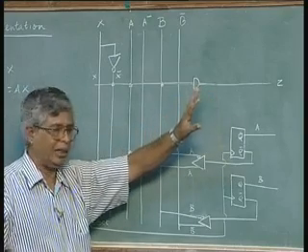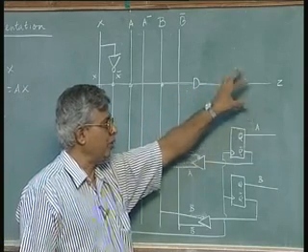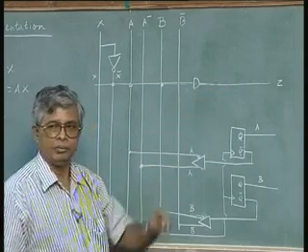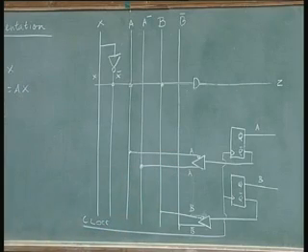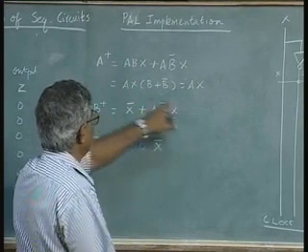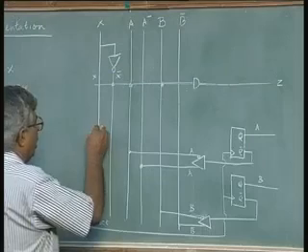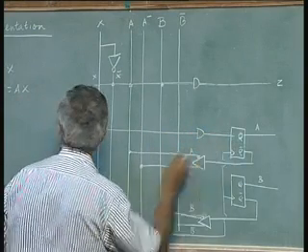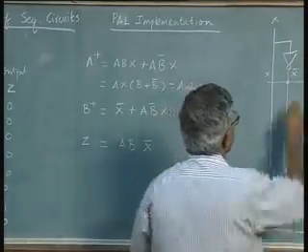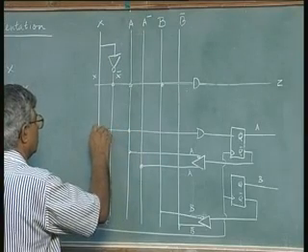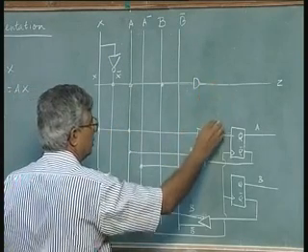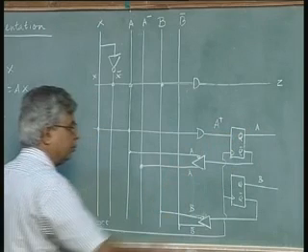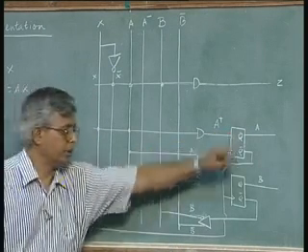Actually, in a practical device, there will be an OR gate output. The OR gate will have several inputs. Each of the inputs is an AND gate combination. Coming to the second, A plus, that is again very simple. It is A X. So I am going to have another AND gate used for this purpose. A X. This is my A plus, which becomes A after the clock. The next state value, present state value.